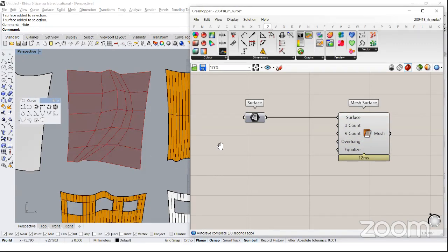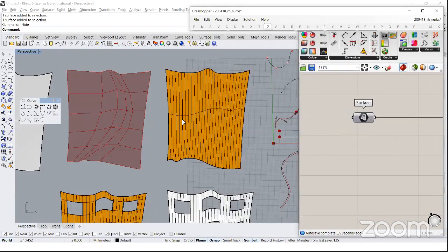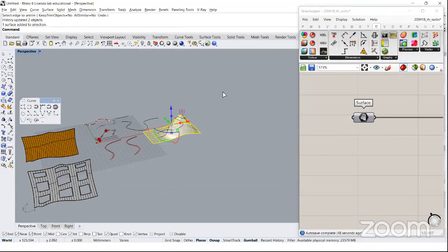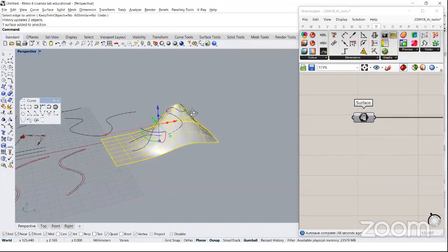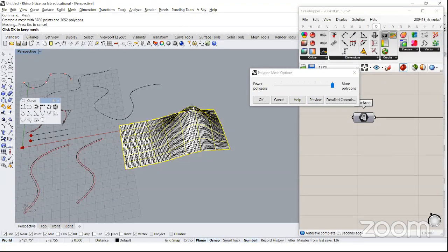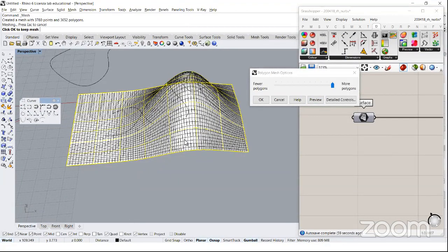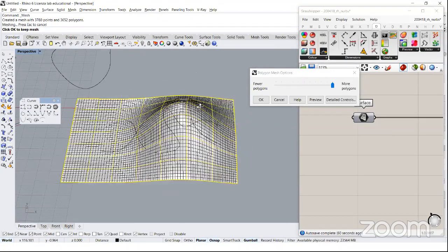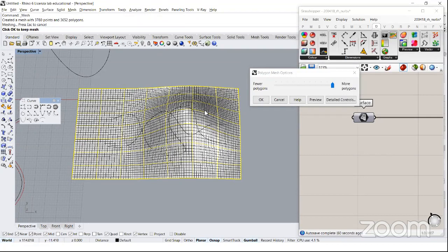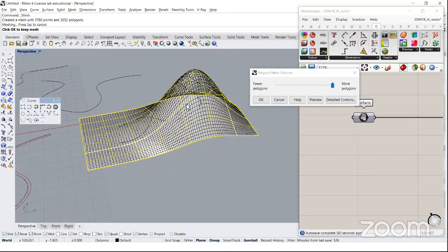So for example, let's take a look at this. Okay, so I'm going to untrim this like this. Let's go back to the original surface. And I want to extract a mesh from this NURBS object. Okay, and so I'm getting this. You see that the topology of this mesh, as regards the orientation, in general, yes, it depends on the NURBS topology, but the object that you create here can also be topologically extremely different from the NURBS one.